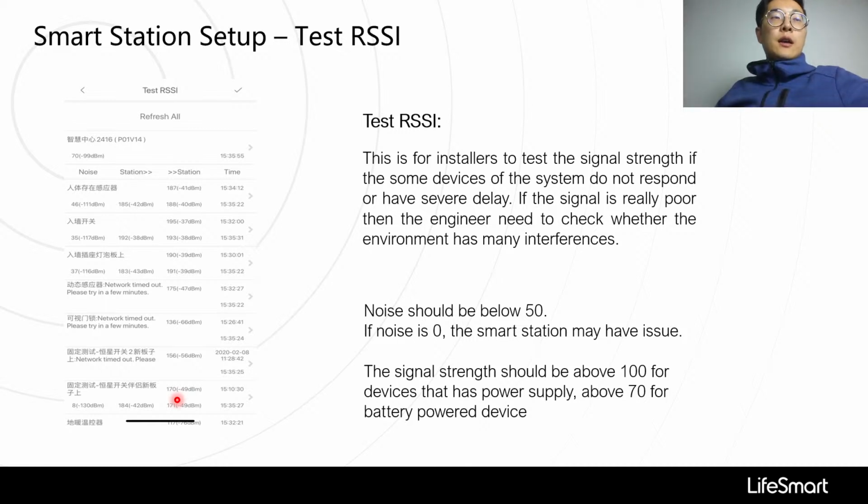If you check the RSSI menu, if the signal strength abides by those standards, then we think you have accomplished a very stable system. So the wireless signal should be okay when users are using it. So that's a very useful function for wireless products to test the RSSI to check whether the wireless signal is good.